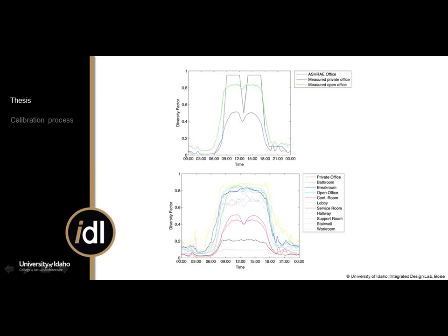You specify a maximum in the energy simulation model, for example, 800 people. At this point, 40% of that 800 people are inside their private offices, and about 80% of that people are in the open office space. So that's how a diversity factor tries to take in the variability on a daily basis in the simulation model and get accurate results.